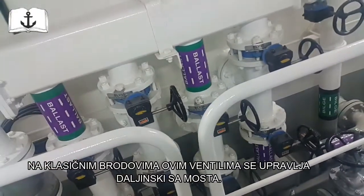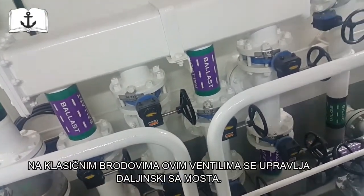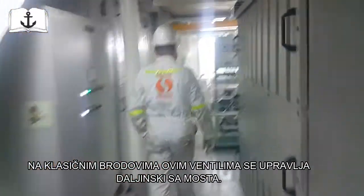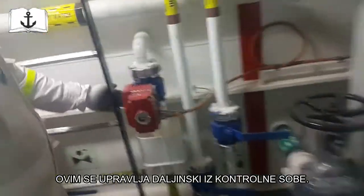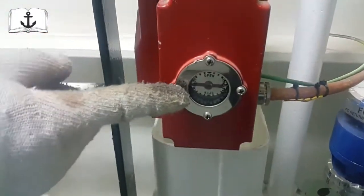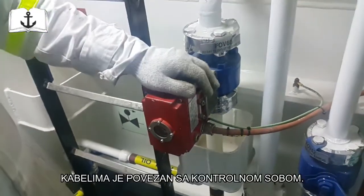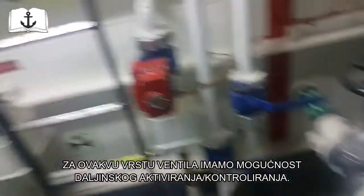These valves, usually on ships, depending on the type of the ship, can be remotely controlled. Then you have what you call a solenoid, right? Actually, it's a butterfly valve and there is an actuator. So if you are in the control room, you have the switch that shows the position. It's closed now. You have the cables, so you have the indication, the power, you push the button to open or close. So you have remote control on these kinds of valves.